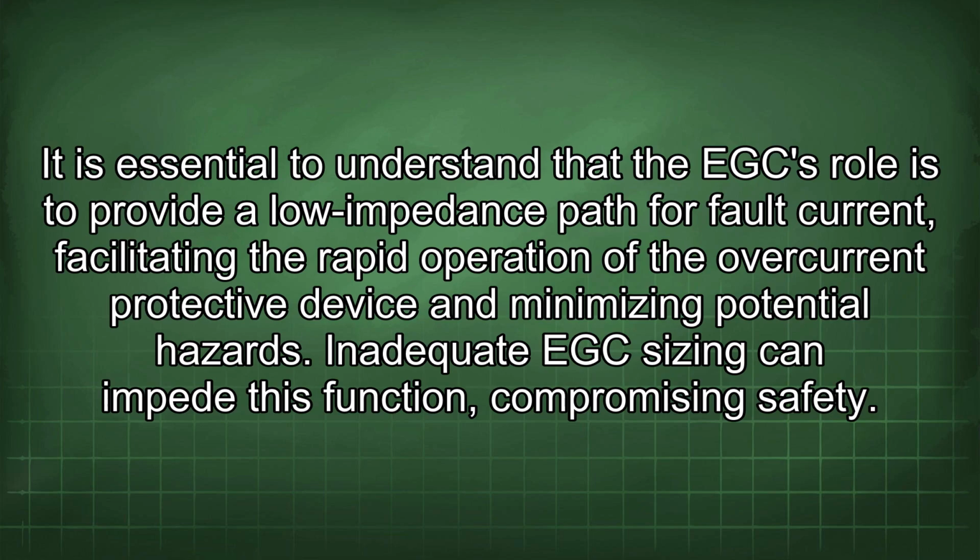It is essential to understand that the EGC's role is to provide a low impedance path for fault current, facilitating the rapid operation of the overcurrent protective device and minimizing potential hazards. Inadequate EGC sizing can impede this function, compromising safety.